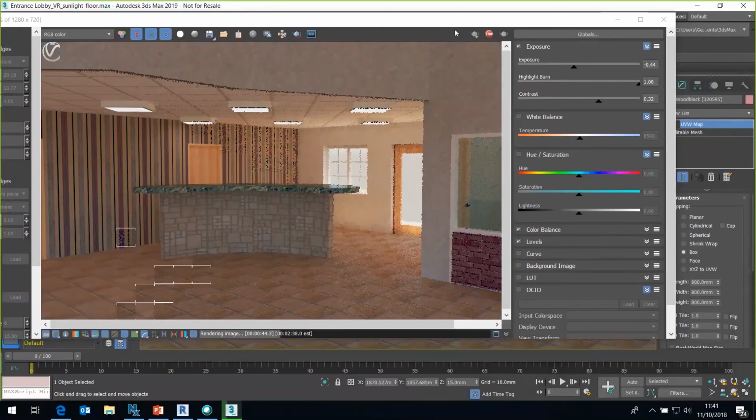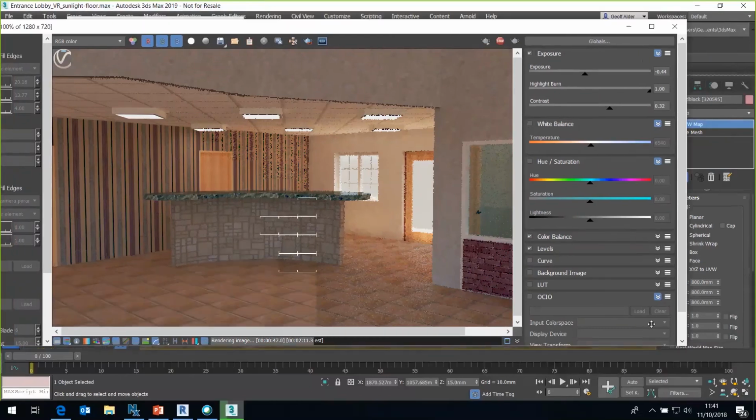One of the areas that is very useful in this render now is these global parameters. Because this image is actually a 32-bit image, I can actually do some post editing in this, and that's through exposure control. I can turn on exposure control, and even adjust that quite significantly.